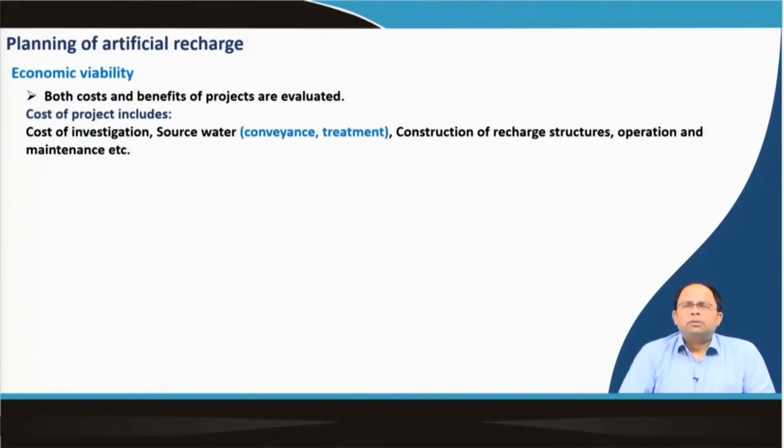Then finally we come down to the main point. Everything else is fine, but if it is not economically viable, then there is no point in doing this particular project. So the cost benefits of the project are evaluated. I was already talking about that earlier. The cost of the project includes everything: the cost of the investigation or of making the plans, source water, conveyance and treatment, that means carrying the water as well as treating it before recharge, construction of recharge structures, and operation and maintenance of those recharge structures. All these things are the cost of this particular project.